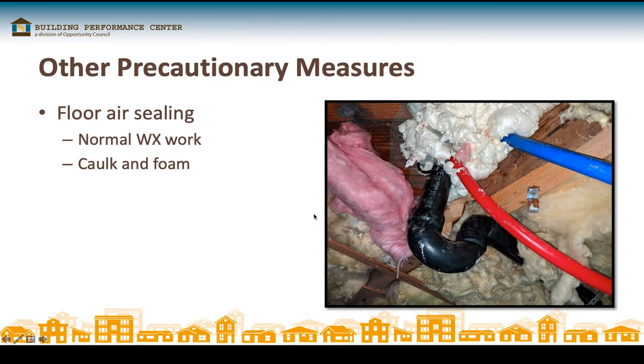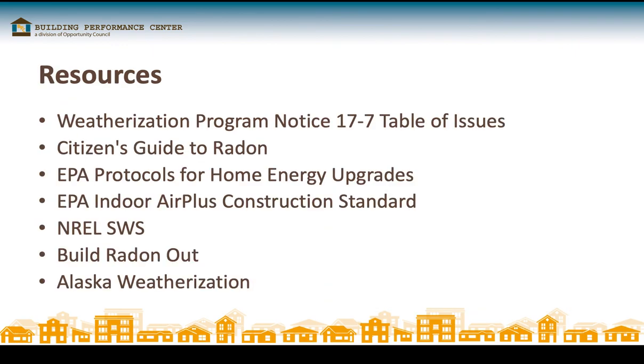Even though you have a closed crawl space, you don't want a lot of air to move from crawl space to house, so we want to make sure that the floor is sealed up. It's normal weatherization work, but sometimes with closed crawl spaces and heated crawl spaces, people do less work because they say, hey, it's a heated space, we don't have to worry about it. Well, we just don't want the air to mix between the crawl space and the house because it could have some of that soil gas in it, and some of the soil gas could be radon.